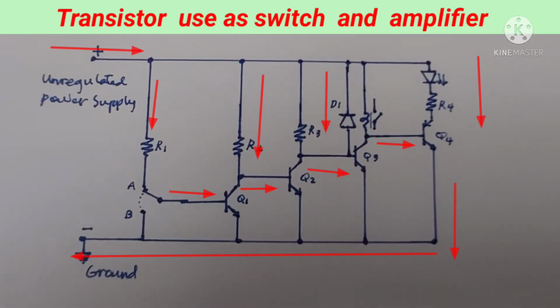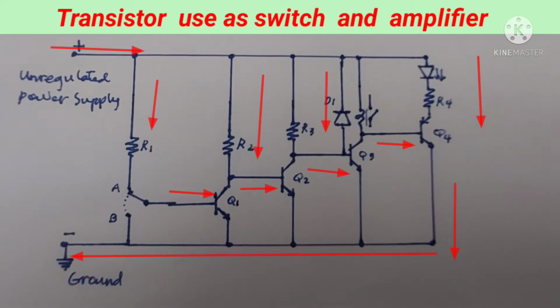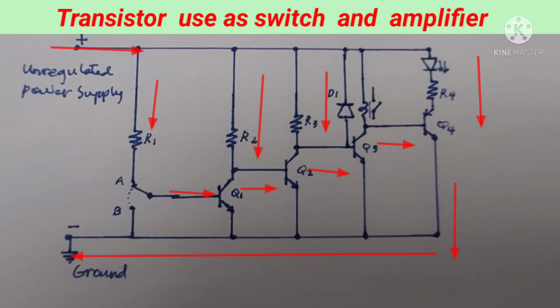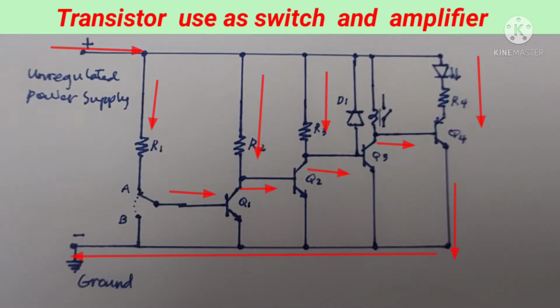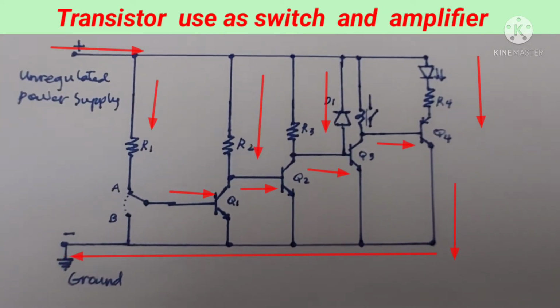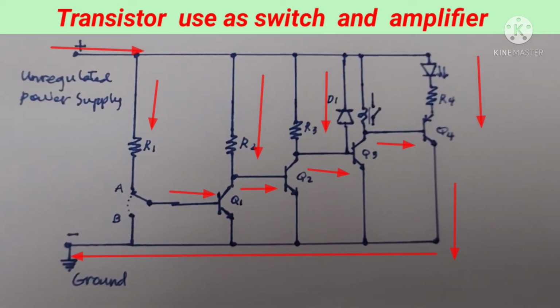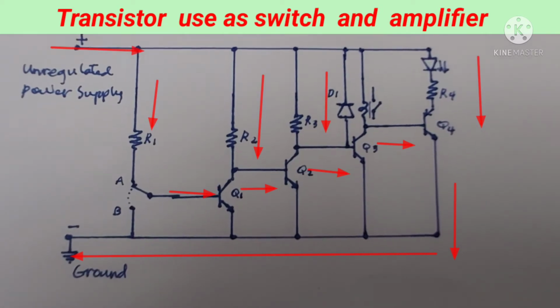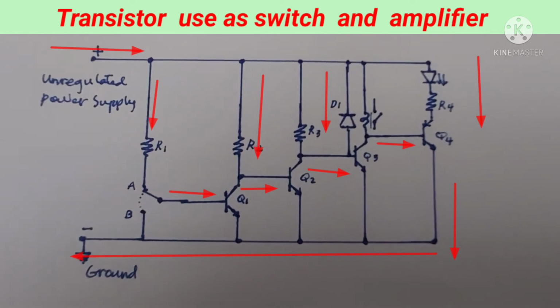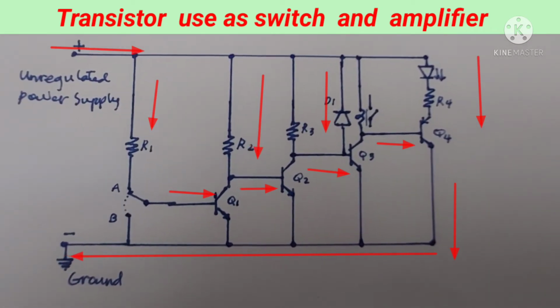I will show to you the illustrations of the transistors in the circuit. These are transistors used as switch and amplifier. If switch A is on, R1 is the bias resistor applied to the base of Q1. The Q1 output is applied to Q2. Q2 will not function, will not saturate.